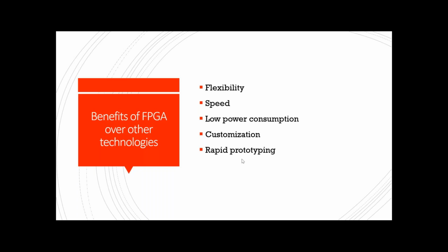And speed. So this speed is not with respect to ASIC comparison. See, again, ASIC is faster than FPGA. I can agree, because FPGA is kind of general purpose, right? So for instance, even if you want to implement a simple half adder using FPGA, there will be a lot of unused logic cells remaining, right? So power wise it's still not an efficient way compared to your ASIC, where whatever circuitry you want for the particular application, you retain that and the rest you will not implement. But here it's kind of general purpose.